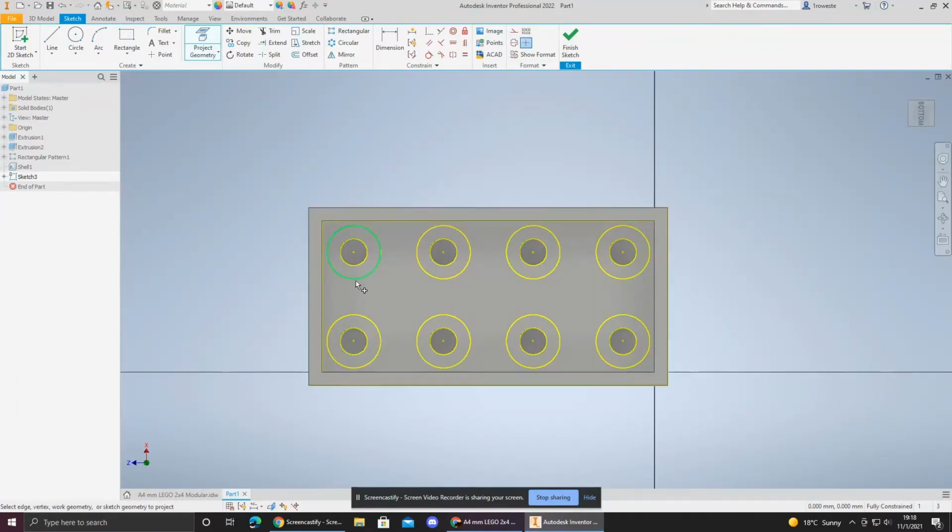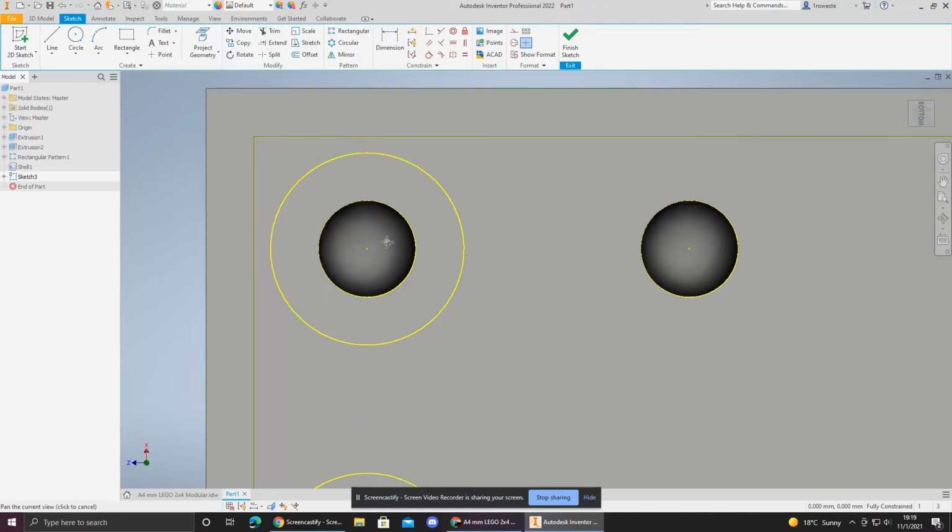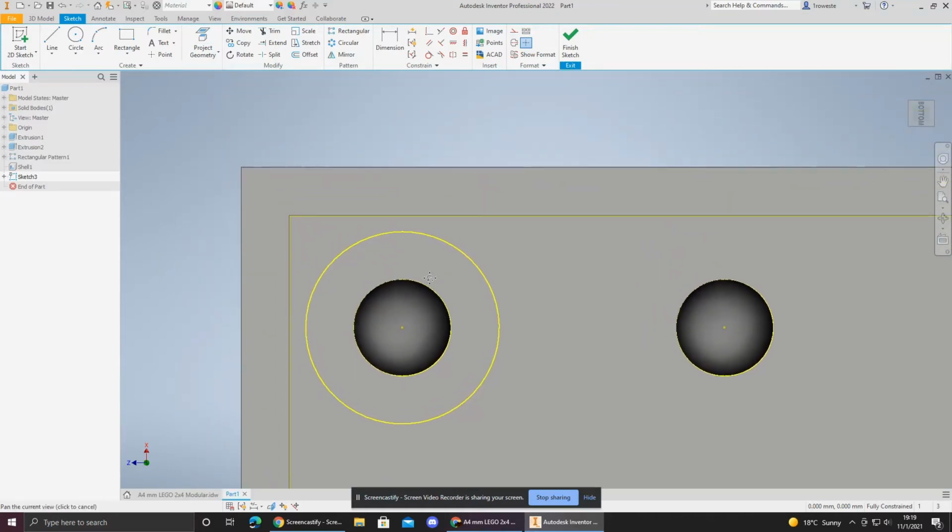After we've appropriately highlighted our geometry, I will delete the unnecessary geometries. We can begin placing our extrusions. There are multiple ways to go about it, however, my preferred method is to simply take a line and draw it up, ensuring that the degrees are set to appropriate perpendicularity, in this case 0 degrees, and simply draw it up to the line which we desire.